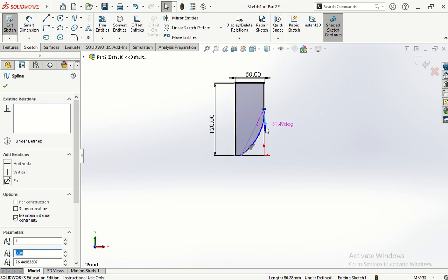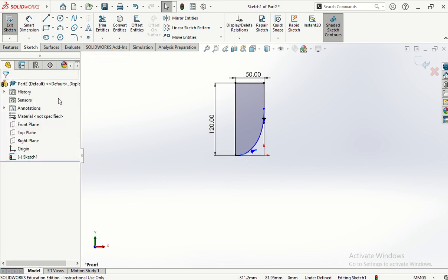So I can control the curvature, and it just gives you something that's an alternative to an arc, which is based on a circle. So if I wanted that to be tangential with this vertical line here, I would take the diamond, and I would then make it to be vertical in relationship to its curvature. And then for this one here, I can control the rest of the curve with that. You can also elongate it and shorten it depending on what you think works. So I'm happy with that spline.